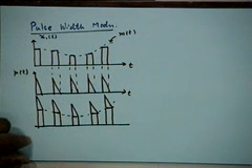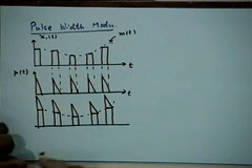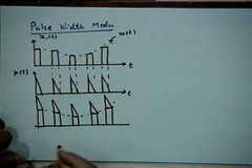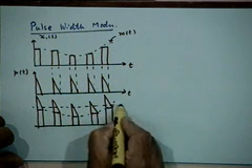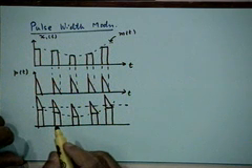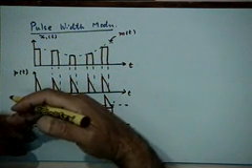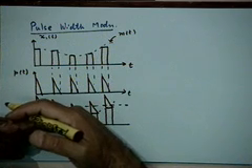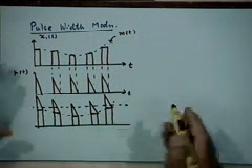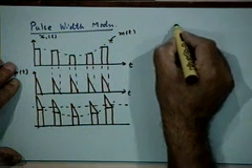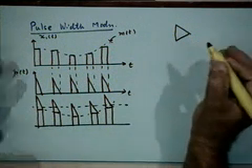Okay. So, you are likely to generate a waveform like that when you add up these two. Having done that, all you need to do is slice this waveform at some point, have a threshold, and pass this through a comparator. Let us say you have heard of a comparator. A comparator is a device; basically an open loop operational amplifier will serve as an excellent comparator.